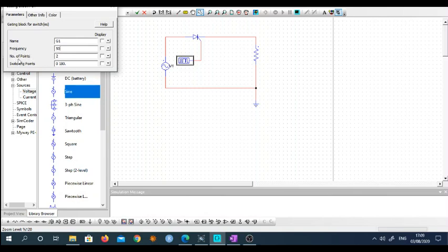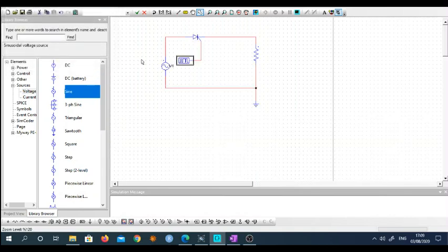And this is very interesting, the number of points where I want to trigger the SCR. So I need the SCR to turn on at 2 points, one at 0 and another at 180. Okay, at 180 I want to make it off, at 0 I want to make it on. So instead of 0, you change this angle. So let me make this angle 45 degrees initially, and that's all.